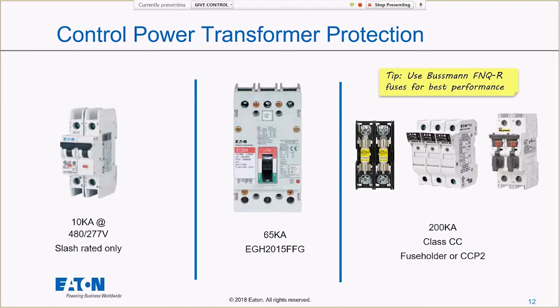I think that there are a lot of times where you have fuses in there and you never really need to use it as a disconnect, and it is absolutely a-okay to use a fuse holder like that in those scenarios. But in front of a control power transformer, what's the easiest way to fix something in our control circuit? It's to turn it off and turn it back on again, right? So having an actual switch there can be extremely valuable.